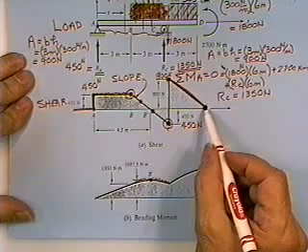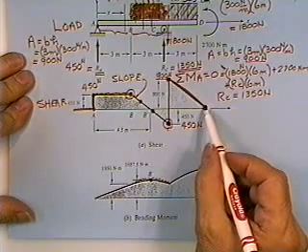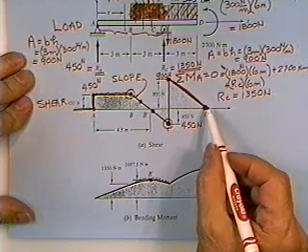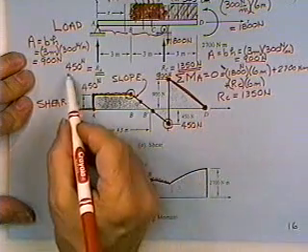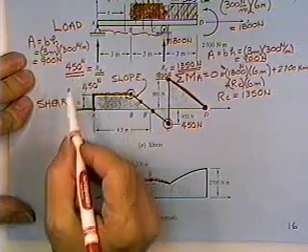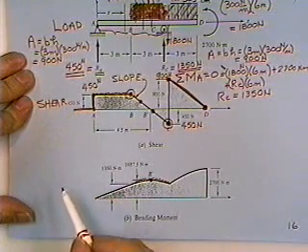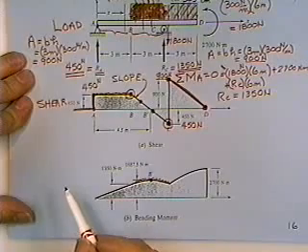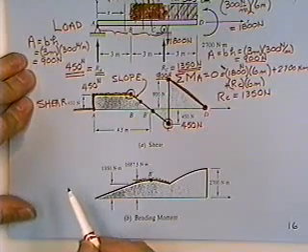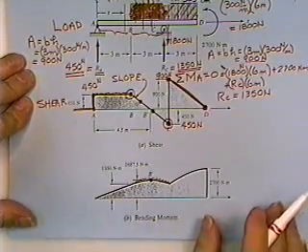That's not to say that the 2,700 didn't affect the shear diagram, because the 2,700 affected the reactions, and the reactions greatly affected the shear diagram. So that torque, that twist, that moment did influence the shear diagram. It just does not make it kick up and down as you cross that concentrated moment.